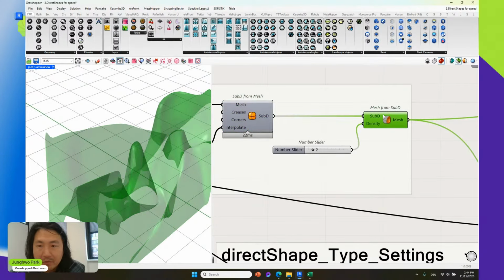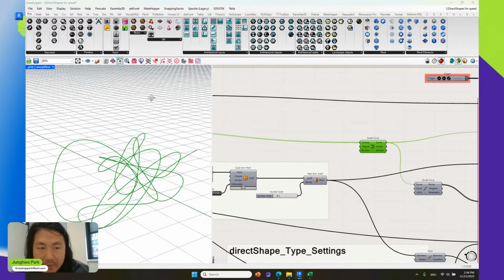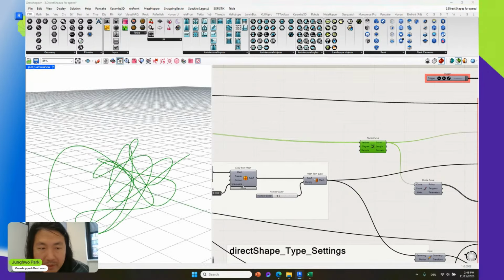And so you can actually bring not only those kinds of surface or mesh geometry, but even points or a mathematical curve, like a NURBS curve, for instance, from Rhino. You can just shoot, and as you can see, we have those lines as curves as a graphic representation. You can bring them into Revit.